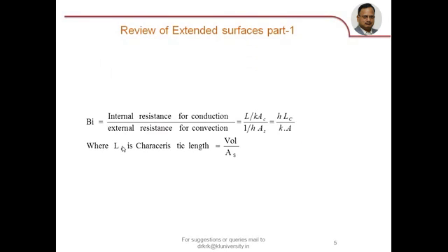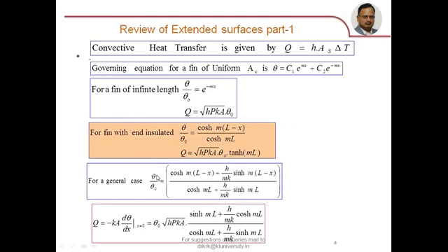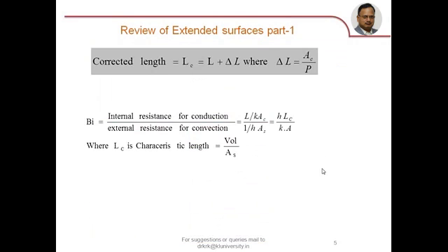Now, when you consider a general case, the equations to determine either temperature distribution or heat transfer are tedious. And in general, no fin is of infinite length. So most possibly, a fin with end insulated case will fit the original one because the end surface area is very, very small. It is almost as if the fin is with end insulated, even in the general case also. With that criterion, what we will do is consider a fin with end insulated, but the end heat transfer may sometimes not be so small as to neglect it.